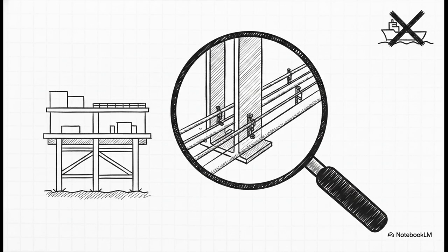A fixed platform, by contrast, has no hull to classify. You don't have to prove to a marine society that the facility is going to float, because it's a permanent steel structure standing on legs tethered right to the seabed. Consequently, the entire compliance focus for your Ex Equipment Register shifts. Instead of marine interfaces, your documentation ties much more directly to structural steel drawings. This establishes exactly how your equipment supports and cable trays route along the topside steel in the jacket.